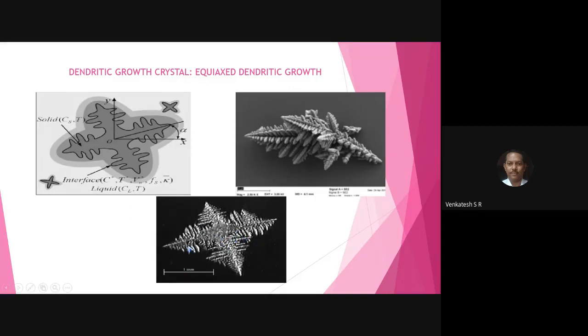This is the actual aluminum liquid solidification process, and how the growth takes place in the mold cavity. Observe here, this is 1 millimeter length. How the growth takes place in the liquid metal. That is, the nuclei attract the neighbor nuclei and form the crystal. This photograph was taken with a scanning electron microscope, SEM.